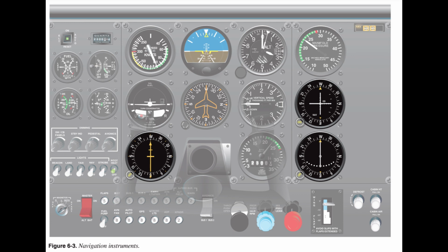Bank changes are made by changing the bank attitude or bank pointers by precise amounts in relation to the bank scale. The bank scale is normally graduated at 0 degrees, 10 degrees, 20 degrees, 30 degrees, 60 degrees, and 90 degrees and is located at the top or bottom of the attitude reference. Bank angle used normally approximates the degrees to turn, not to exceed 30 degrees. Power control.